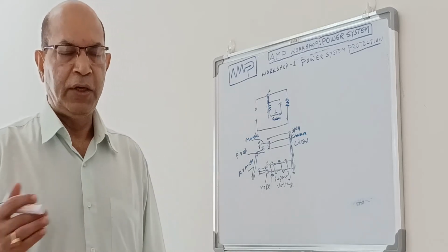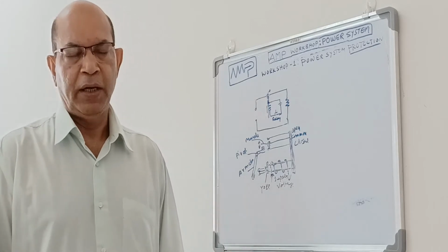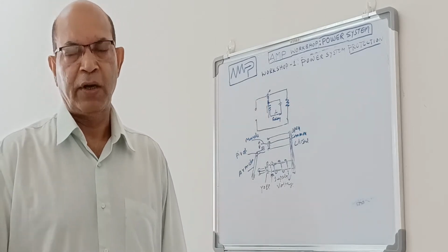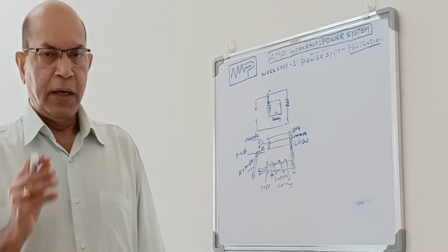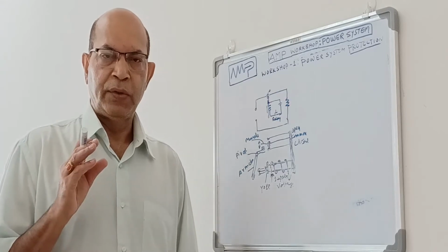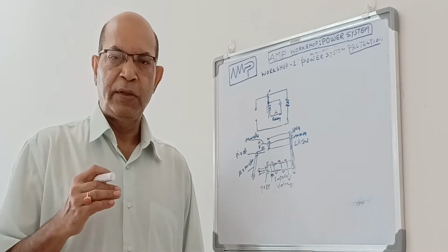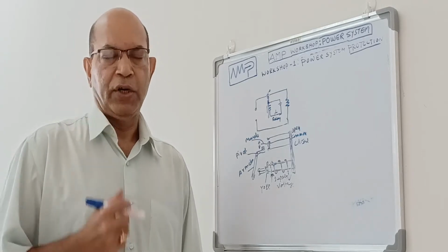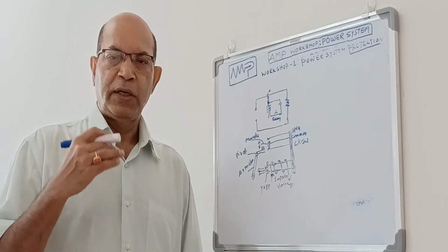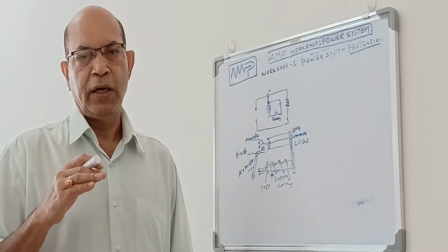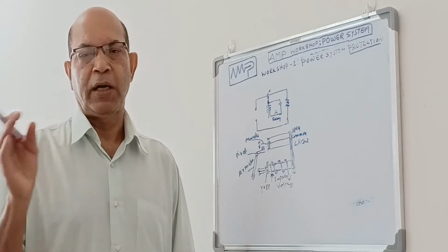Now, before going into further details, we need to discuss what this relay is, before going to individual types of relay and their architecture, working principle, advantages, disadvantages, all this. Now, a relay is a small control device which is activated by a small power supply, and on activation, it gives some command or output contact which can control a power circuit. That power circuit means it can open or close the breaker, or it can be used for multiple control of multiple circuits by a single device. It is able to control multiple devices.